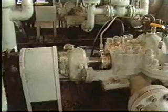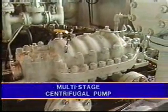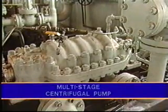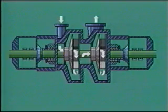That's where multi-stage pumps come in. They have two or more single suction impellers mounted on a single shaft. The discharge port of the first impeller is directed to the suction port of the second, and so on through additional stages. When the fluid flows from one stage to the next, fluid pressure is increased.